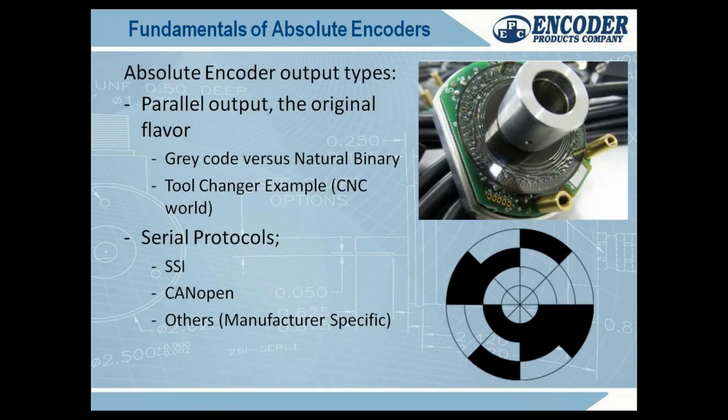So that's it. That's the meat and potatoes of how an absolute encoder works. Now, my 3-bit disk here, this is an 11-bit. This is our model 960. As you can see inside, it just has those photo receivers, which are right here on this metal plate, and it's just shining light through. The light is actually above, on that board with the LEDs, taken off. But this is the receiver, and it's just counting the light or not of each unique position. Well, that's a lot of tracks.